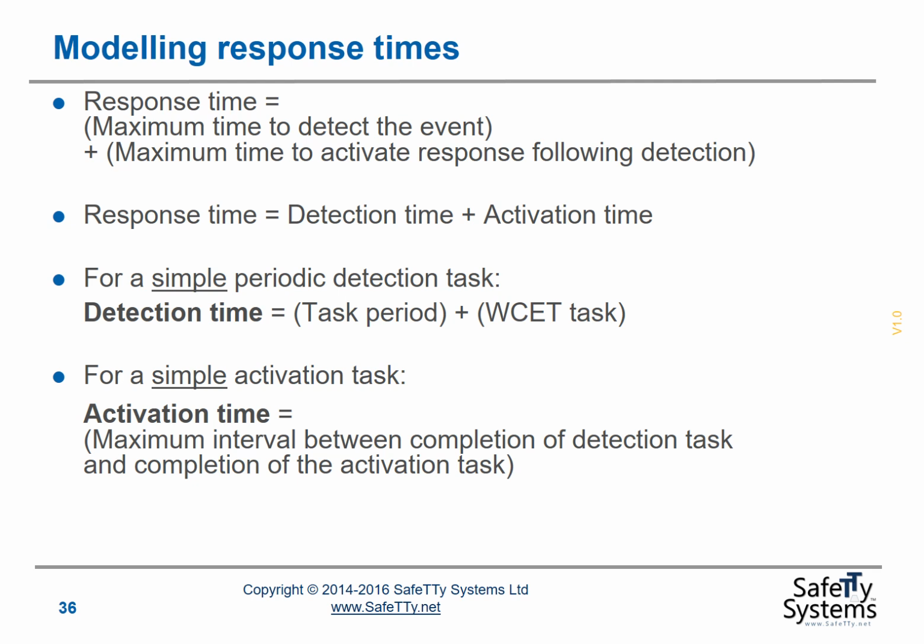We can start by saying that the response time is equal to the maximum time taken to detect an event plus the maximum time taken to activate a response following detection. In other words, the response time is equal to the detection time plus the activation time.